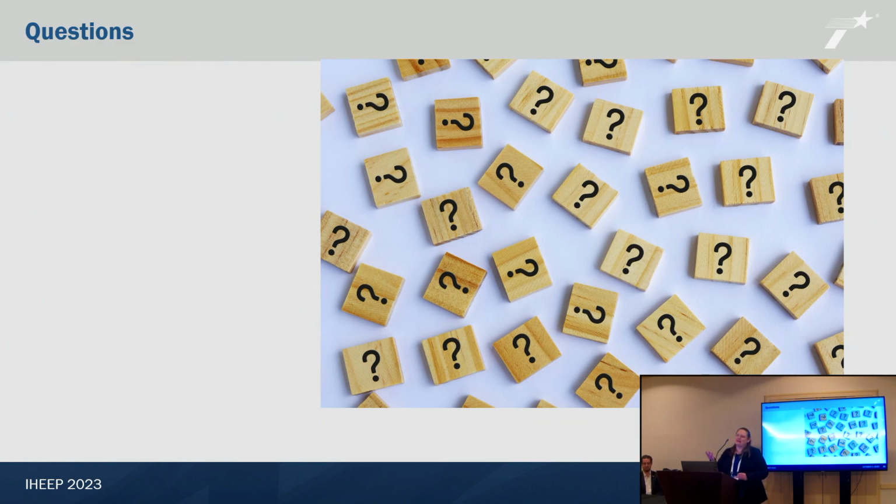And so there's been those discussions, because to do a drone or LiDAR or something, it's really hard to get that tolerance. And they're like, do we really have to put people out there with stakes? I'm like, we need a 1/4-inch tolerance when you're constructing it. If you're off a 1/4 of an inch here or there, trying to place beams and things like that could get difficult. Part of the research that we're doing is going to be aimed towards what we need from an inspection standpoint from the bridge stuff. Our survey group is more involved in trying to figure out the details with how many images and stuff. But again, it's all in discussion at the moment.